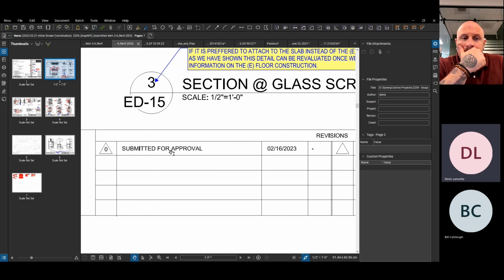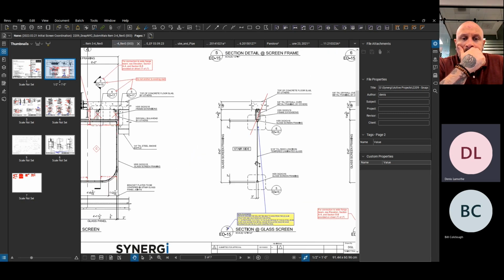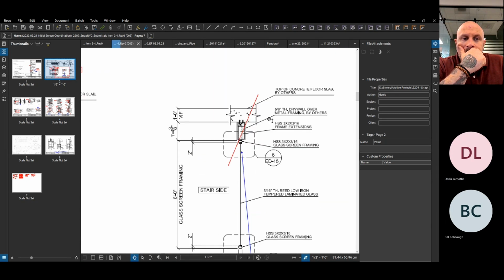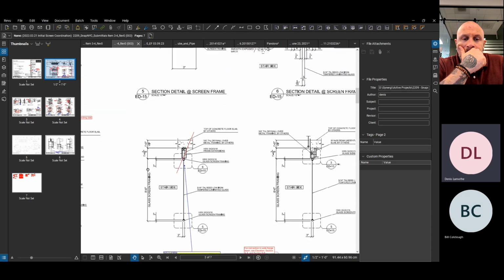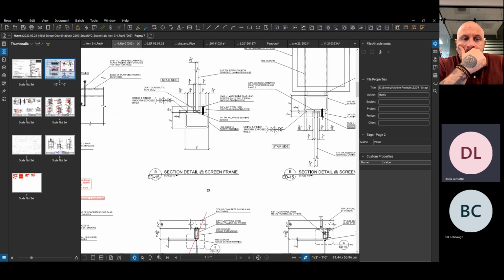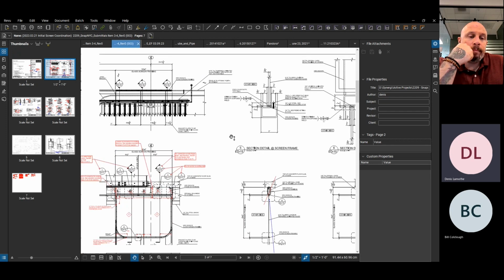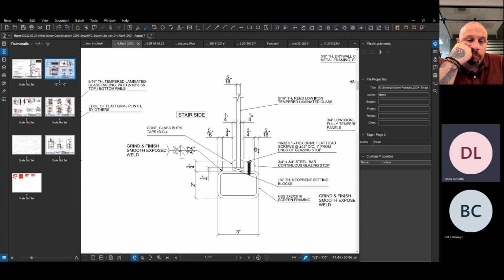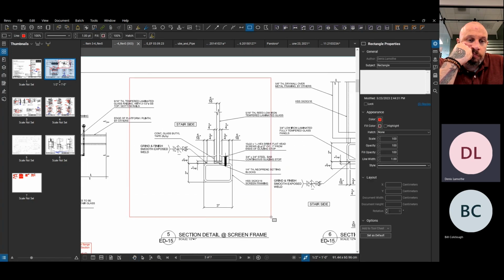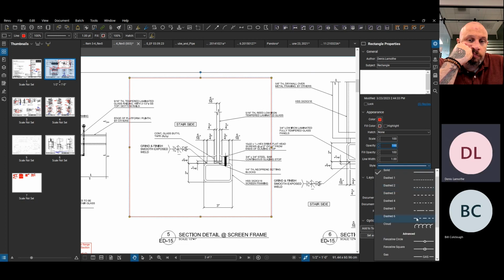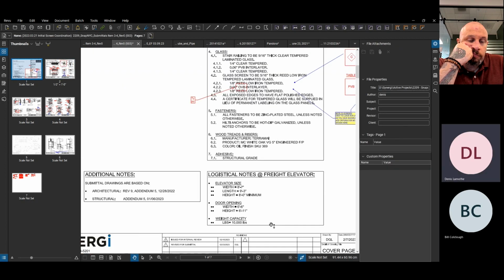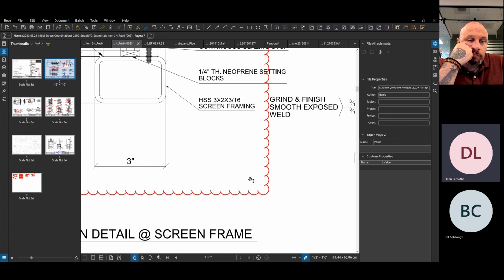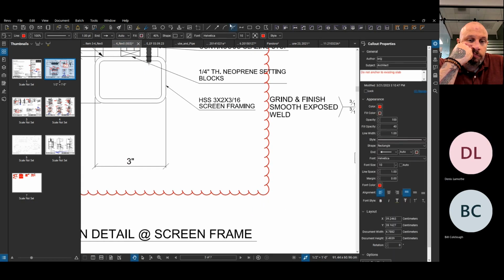In this case, this is the first submittal, so I obviously don't have anything in here that I've revised and clouded, but that will come up at some time when you're working on these drawings, whether they're assembly drawings, application drawings, or erection drawings. If a dimension changes, or if the entire detail changes, then cloud the entire detail, and add that little triangle here. That would look a little bit like, not that.